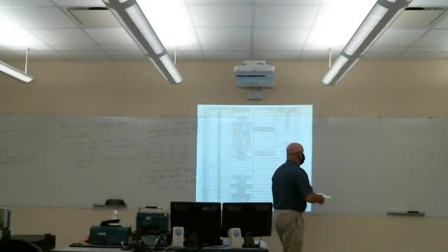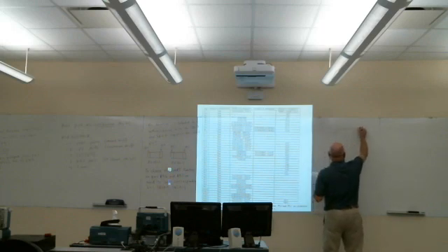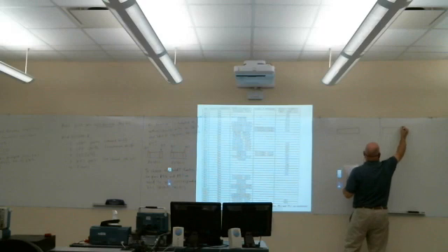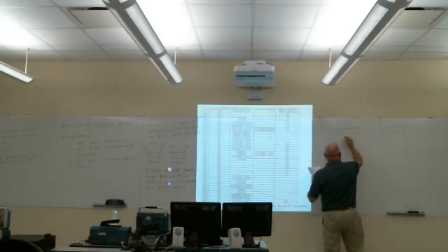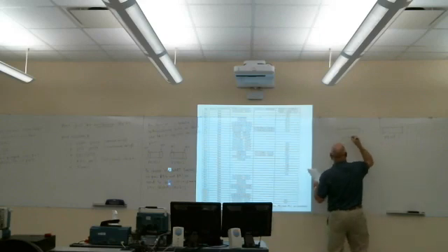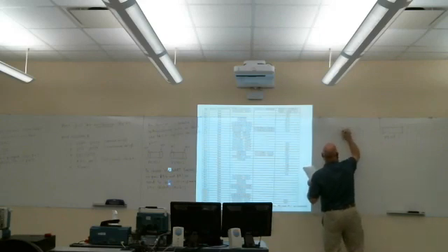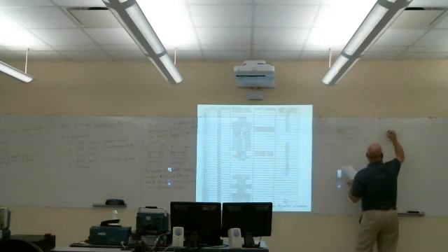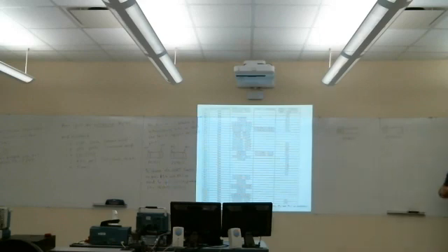So what I recommend that you do is typically start out with: okay, this is what I need to do. I need to make sure that P9 selection 1 and P9 selection 0 in bits 7 and 6 have zeros and ones, respectively, in those particular registers. And ideally, when you do this, you want to affect only those 2 bits in these registers, right? You don't want to change the functions of the other pins.